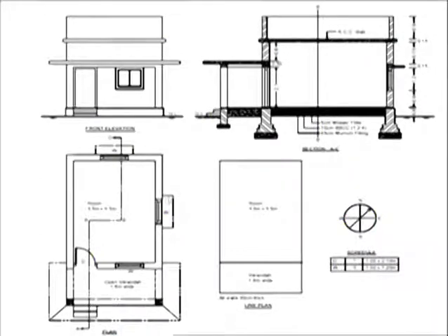Okay, sometimes we may provide the beam. So the center line of the beam is to be provided. The end supports of the beam should not be above the opening. That we have to take care of. So this is how we can prepare the working drawings, plan, section and elevation. The schedule of doors and windows is to be drawn.